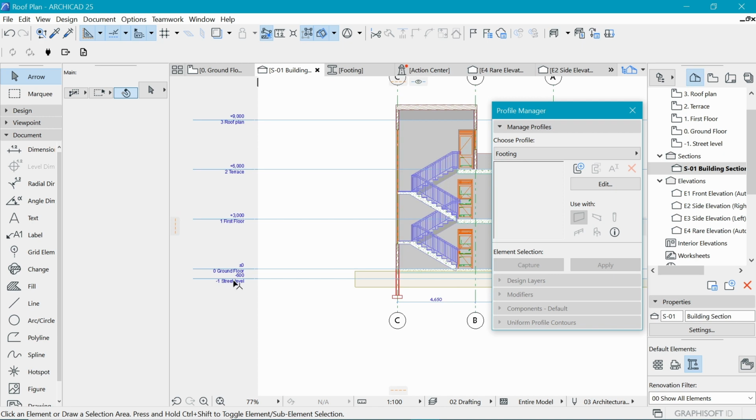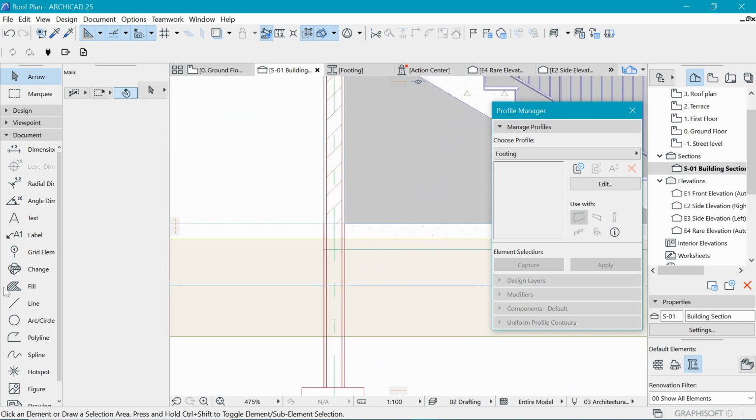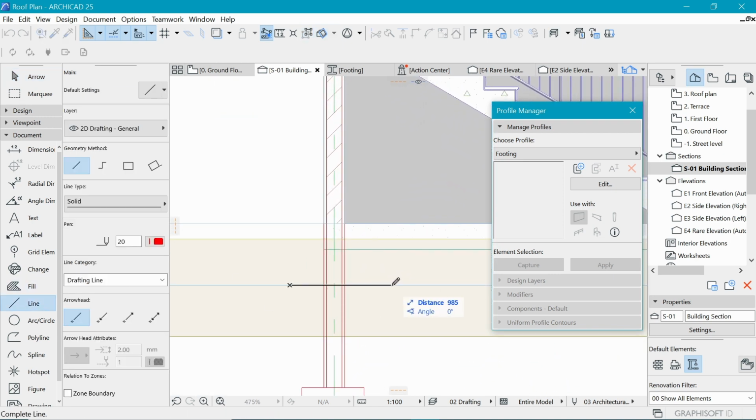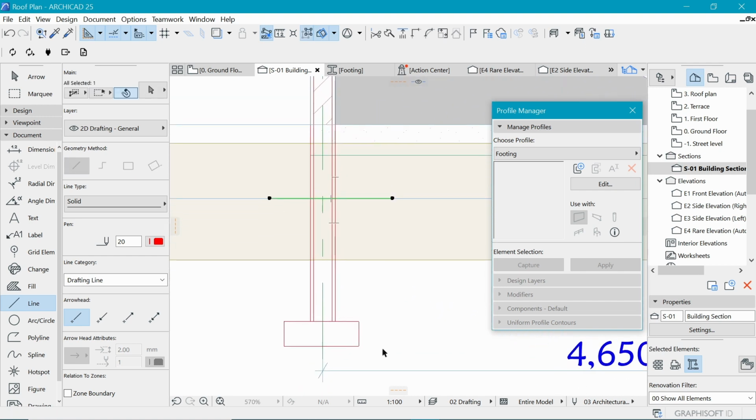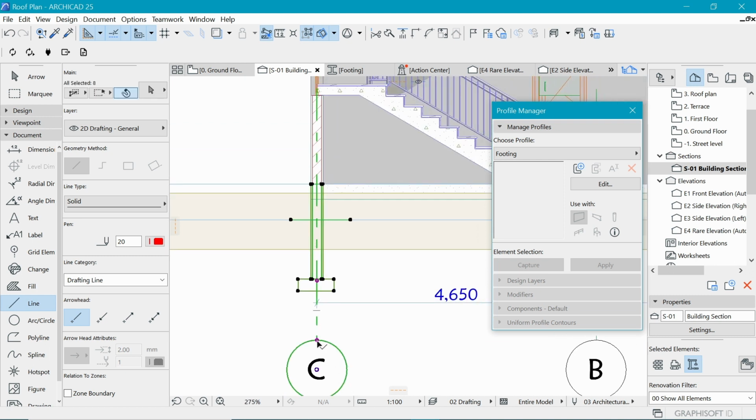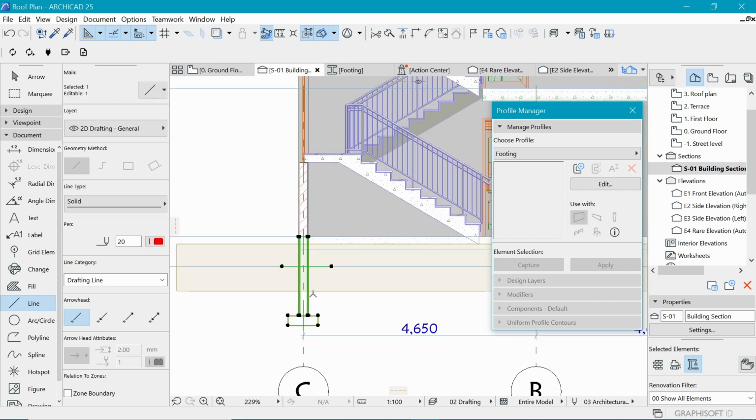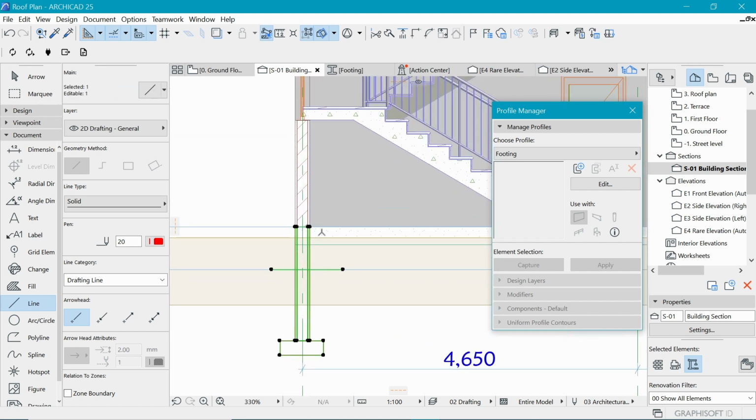And then we can see the street level is somewhere here, so I'm going to draw a line that's going to help me identify where that wall should be drawn. So I hold down shift and select also the rest of these things except for that grid, which has been selected automatically, so I will deselect that. So that line is going to help me.